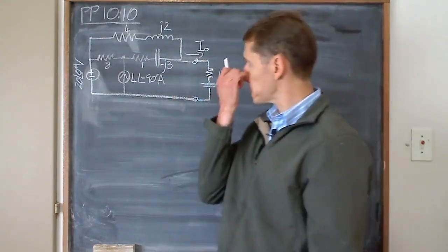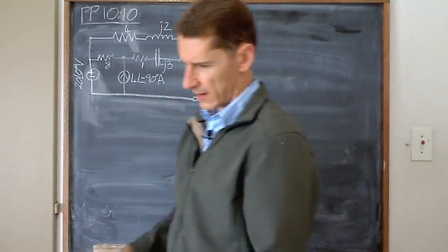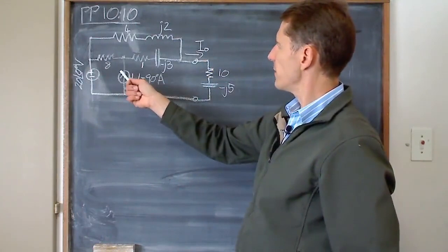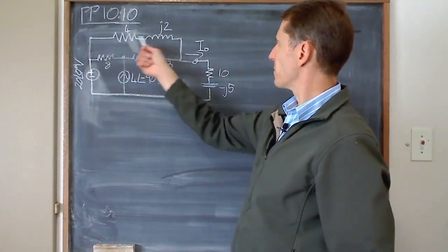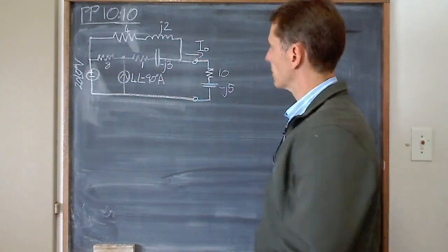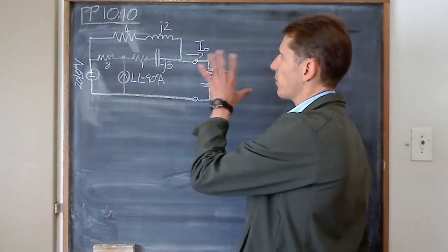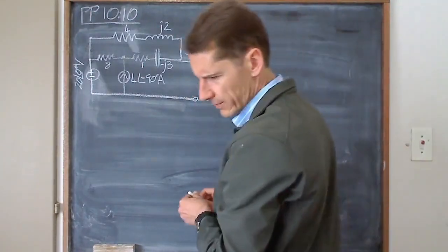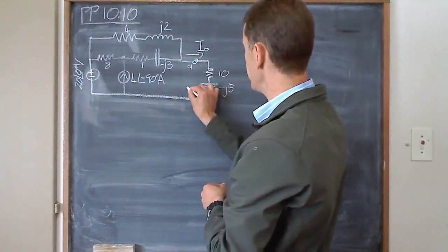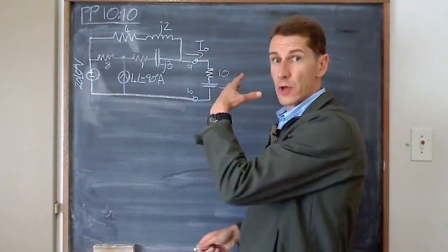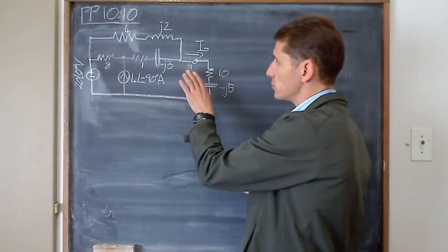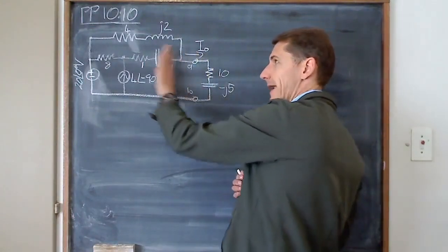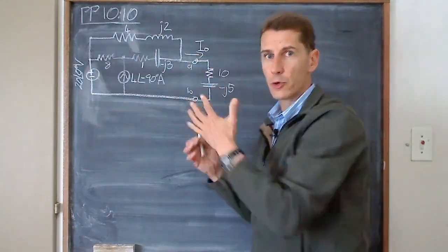So here's our last circuit. 2 sources in there, a voltage and a current source. A weird branch crossing over them. Don't look at this as a Y or a delta. We're not going to use that. So they want us to get the Norton equivalent between terminals, which we should probably call A and B. Once you have the Norton equivalent between these 2 terminals, that's your load. Norton meaning we're only going to look at that part of the circuit. This is like your load connected to your circuit.